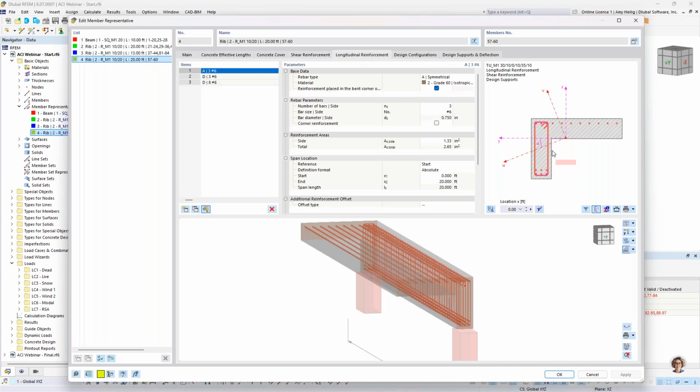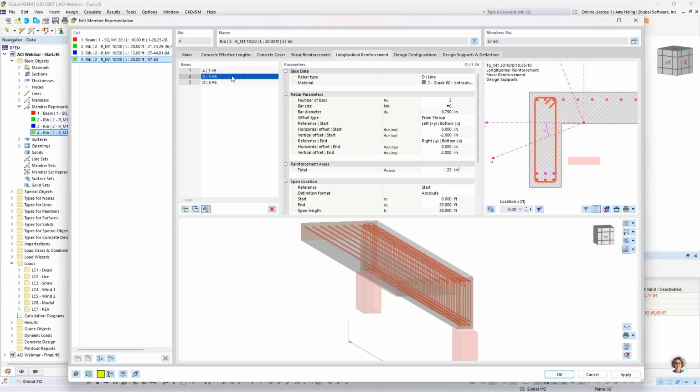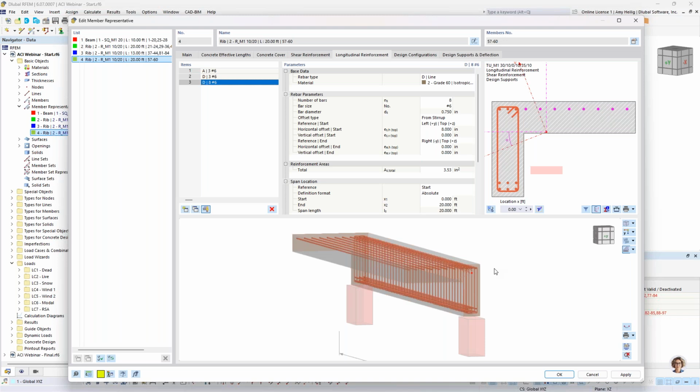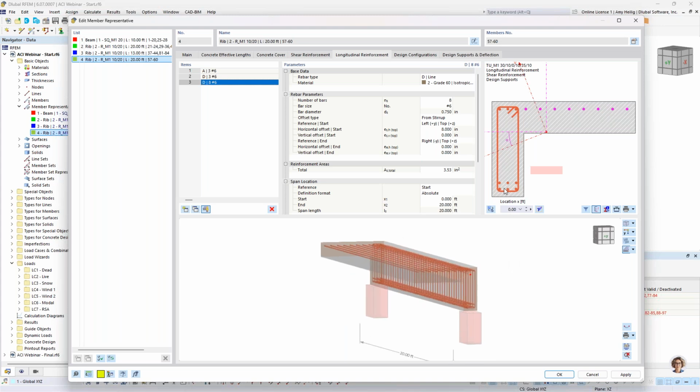The longitudinal reinforcement is going to be a little bit more detailed than what we saw with the columns. You'll notice that I have 3 number 6s set to symmetrical. So this is going to place 3 number 6s up at the top and at the bottom that are currently highlighted. We also have an additional 3 number 6 bars defined here at the bottom with what we call the rebar type line. This line option allows me to place a line of reinforcement, and I can specify the different offset, either left or right or top or bottom, with this input option. And finally, we have 8 number 6s that are defined in the surface effective width itself. This was also defined with the line option. I modified the offset here, such as 8 inches, so that we can input this longitudinal reinforcement within the slab element. So pretty simplified for today, because we'd probably want to create different zones with different longitudinal reinforcement, but this is just a little bit of an overview for this simple example.